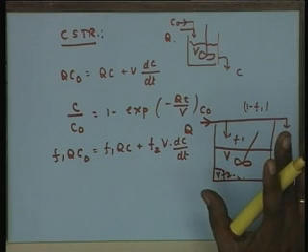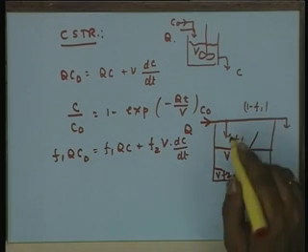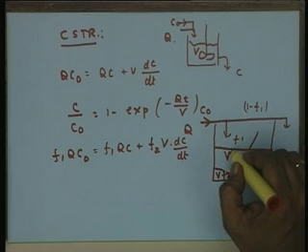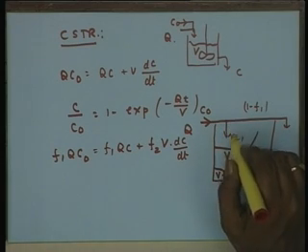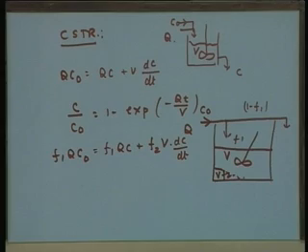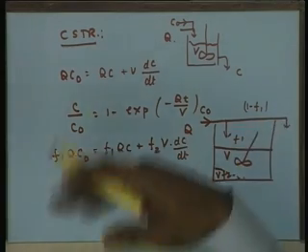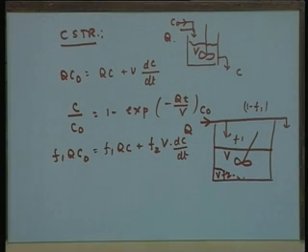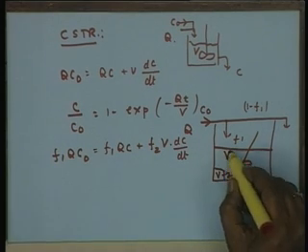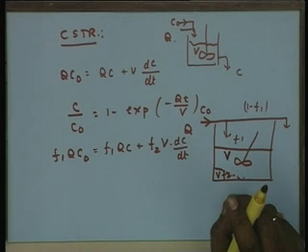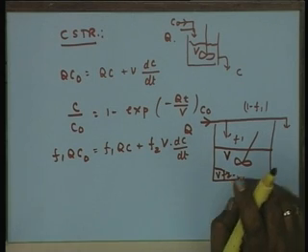No, this F2 is a fraction of the total volume which is stagnant. Here the F2 is not of the total feed stream. Of the total feed stream, F1 has come into the reactor and 1 minus F1 has gone untouched from the reactor. Now, of the total volume of the reactor V, a fraction F2 is a dead zone.